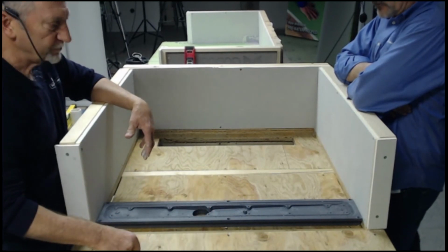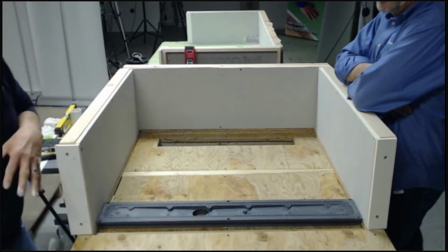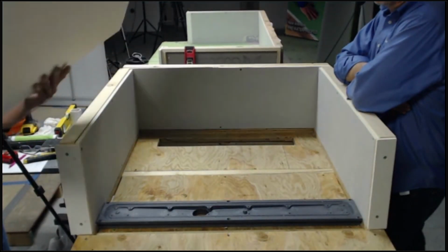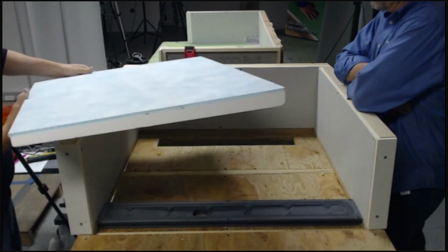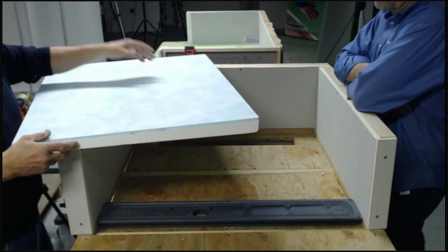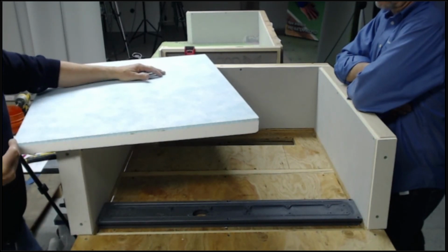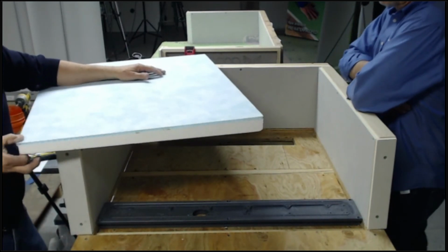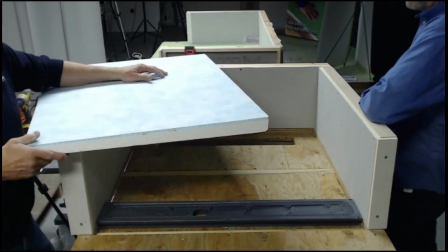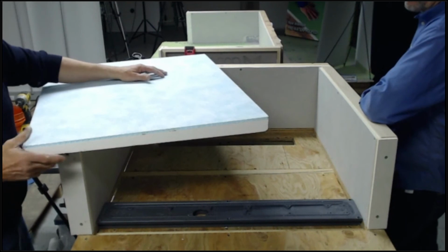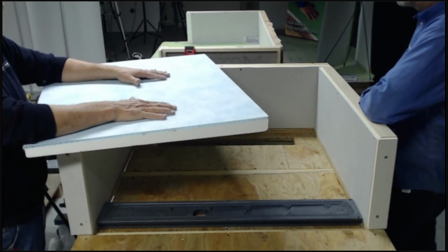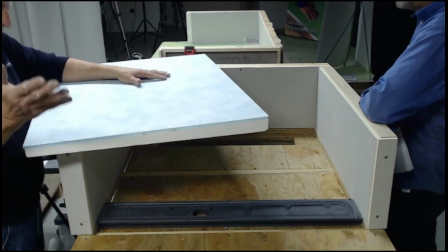Okay, so now as far as the base goes on this, we have our ProBase II single slope, with the same honeycomb composite foam as you saw previously, but this has a 1/4 inch per foot slope built into it. It's 1.25 inches in height at the drain to match up to the drain, and then 1/4 inch per foot slope from there. We have this in a 32 by 60 kit, or a 64 by 64 kit, depending on the size of your shower.